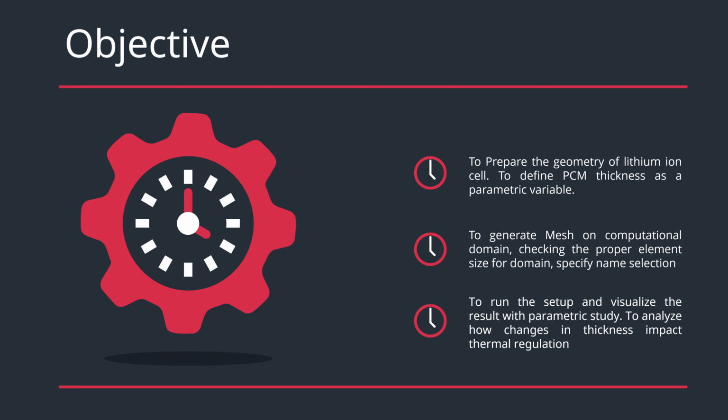Next is to generate the mesh on the computational domain, check the proper element size for the domain, and specify the name selection. Then run the setup, visualize the result with the parameter study, and analyze how changes in the thickness impact the thermal regulation. So these are today's objectives.